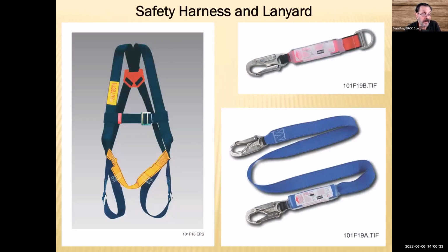Now, for suspending, the harnesses we normally use are Class 3 harnesses, and they are only allowed to be used for a single use of a fall. So you don't fall and then use it again after that for a different protection. Once you've actually fallen with these, you've got to take them out of service.